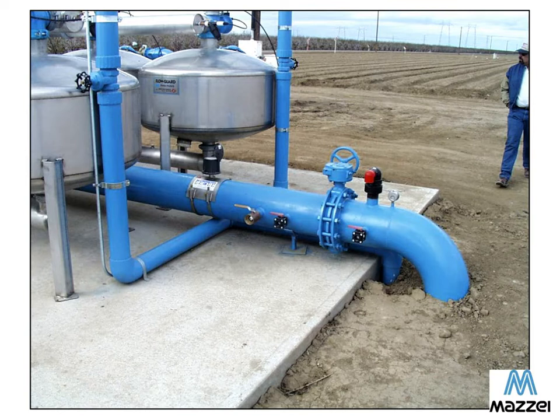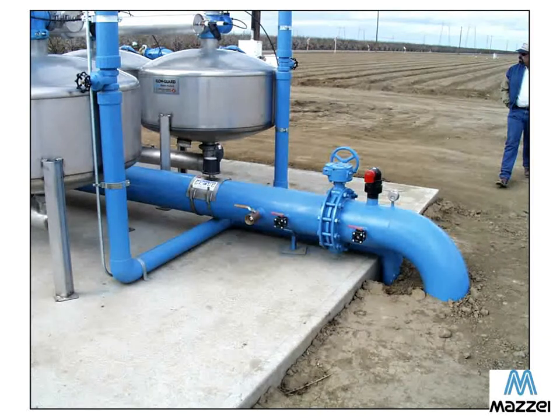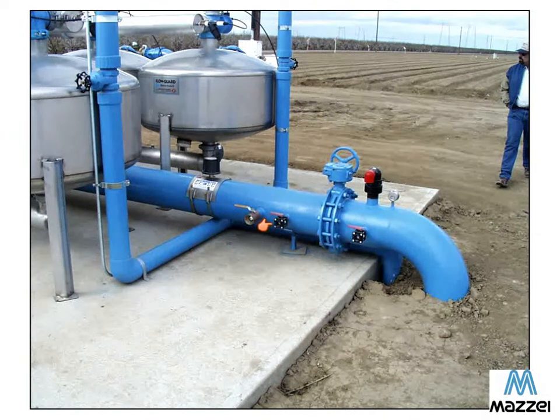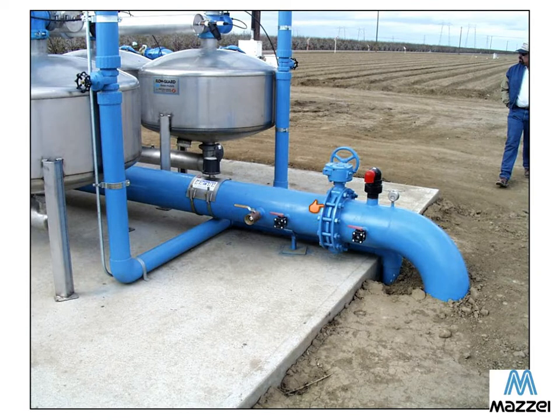So this is an example of what you don't want to see in an application in the field. This pipe is probably 12 inches in diameter and supplying 800 to 1,000 gallons a minute, and it is installed with 1-inch fittings for a 1-inch injector. In order for that injector to pull in the desired amount of material, the differential that needs to be created will be quite high, and you'll lose a lot of pressure in the process.